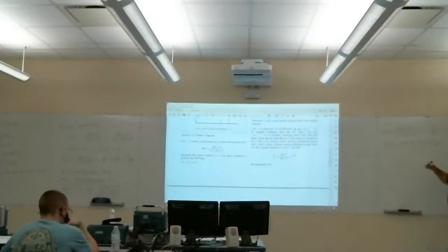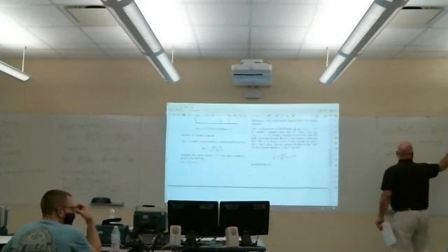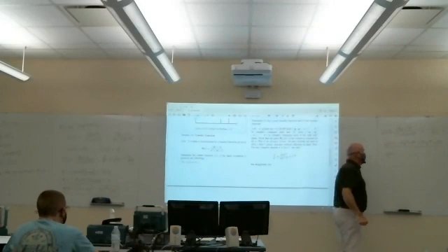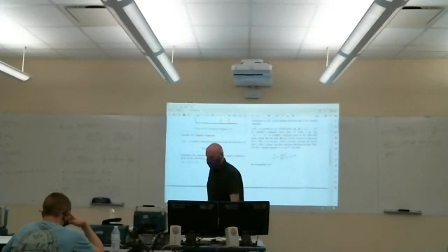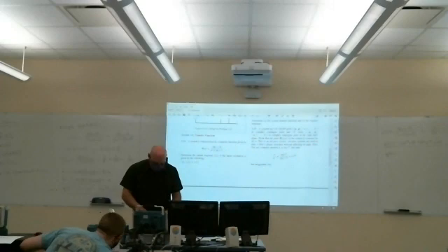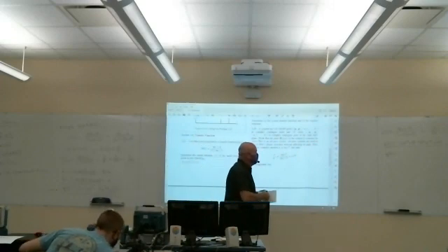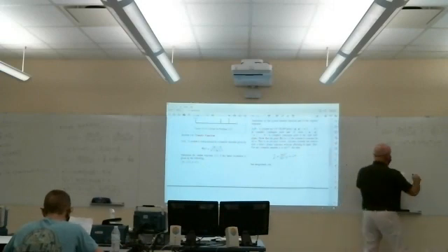Now this is the impulse response. It's not the answer. We know x of t is u of t. So now we pull out our convolution table. What's u of t convolved with -2 e to the -t u of t? Use the convolution table instead. So this is pair 2.